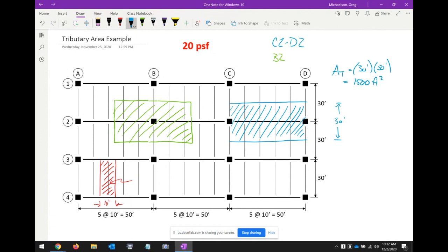What I tend to do is work inwards and work my way outwards, sort of using that whole hip bone connected to the leg bone approach. Do you design according to the floor area or the sum of the tributary areas? Your role is to design the elements in the system. You take each beam and say, this is the tributary area for this beam. What beam do I need to use here in order to safely resist those loads? By designing all of the beams and all of the columns, you're essentially handling the entire floor area.